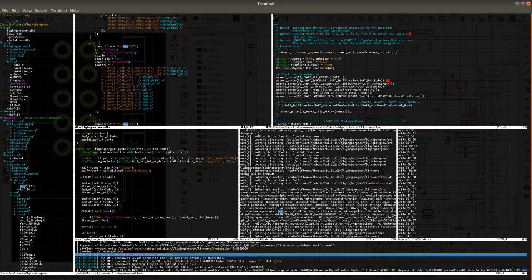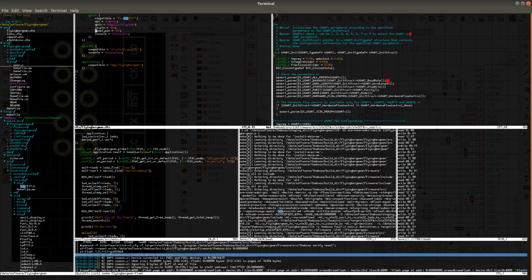I still don't have the driver actually implemented in software, so this is just getting an idea of what it is that we want to achieve. And once I've put the sections in the device tree, I can start writing the code that will actually read the sections and configure all of the peripherals that are involved in driving the DRV8302 chips.